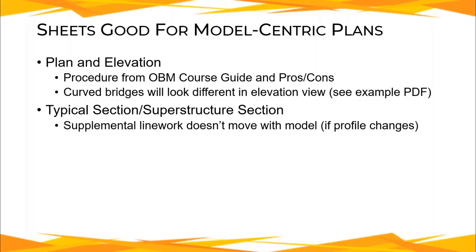Well, if that profile view changes, the supplemental line work that I drew in there doesn't change with it because it's not tied to the model. Now, it's not a huge deal because you can figure out how much the profile was raised or lowered, and if it got raised by 2 inches, then I just select all that supplemental line work and move it up 2 inches in the drawing model, and you're done. So it's not a huge burden, but it's still something to keep in mind and consider when you're going to do these things.